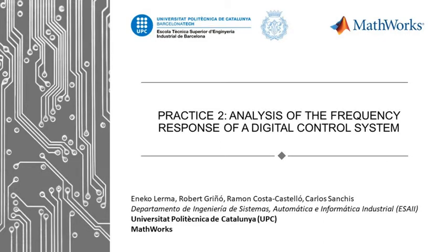Hello. Today we will analyze the frequency response of the LJ Technical Systems servo system. The objective of this practice is to obtain the theoretical and experimental frequency response of the open-loop system. Along with this, we will apply the Nyquist criterion to determine the range of values of a proportional controller so that the system is stable, and we will verify it experimentally.